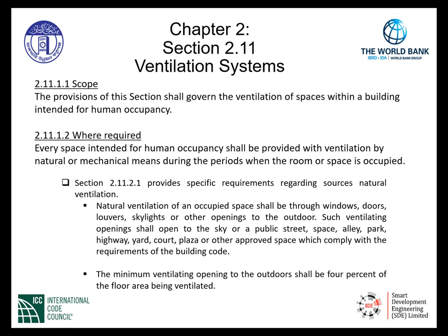A word of caution here: when you have natural ventilation openings, we need to make sure that we do not draw in contaminants such as exhaust from the public streets, things of that nature. So it's up to the designer to properly indicate where these openings are going to be located on the building, again, to bring in clean, fresh outdoor air.